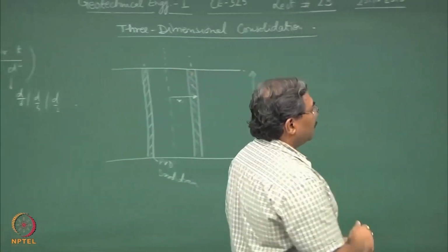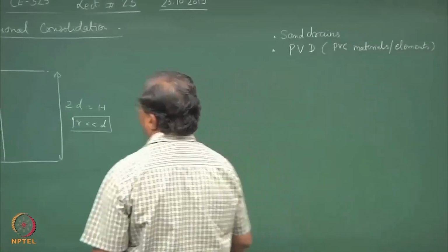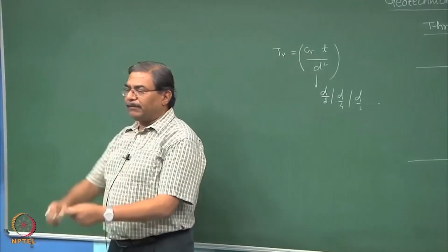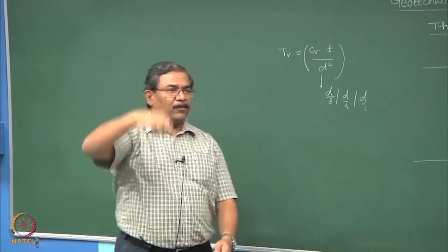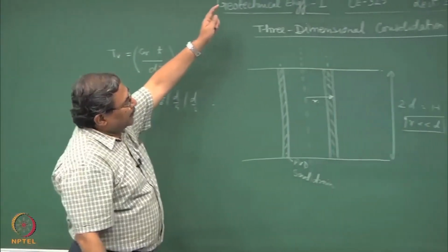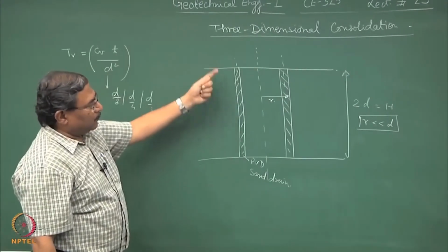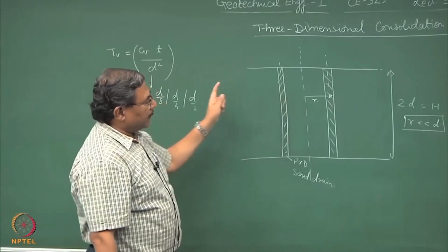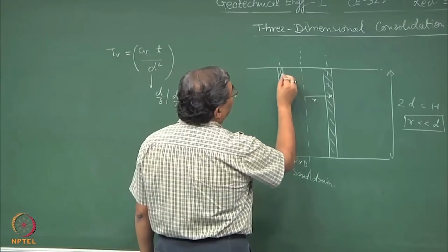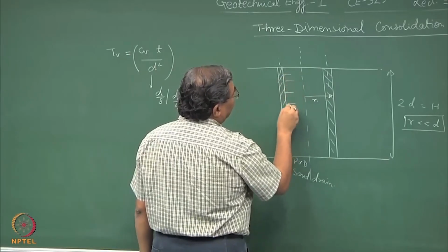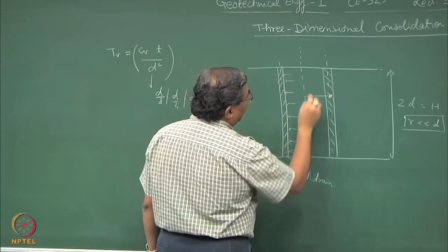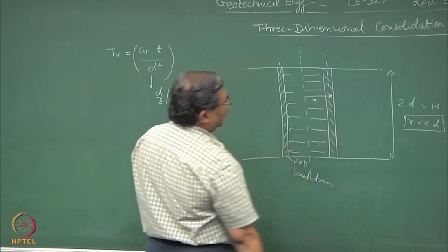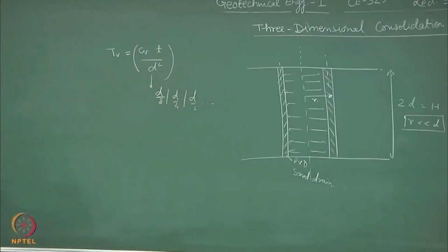This is the concept. So, I am sure you must have seen most of the projects which are being done in the country right now, particularly in the coastal regions. You must be seeing big machines inserting something into the ground. So, with the help of big machines, we can insert the PVDs. This could be up to 20 meters, 22 meters in the ground, and they act as a drain. So, they take out the water. So, the water is now going to get collected in this, and half of this is like this, and hence the consolidation process becomes faster.